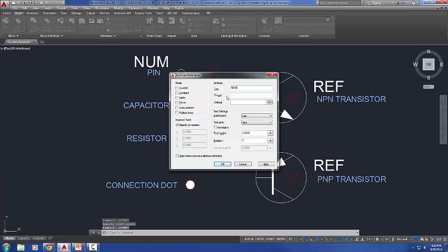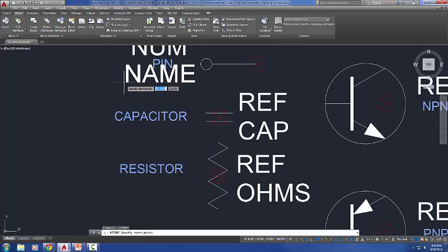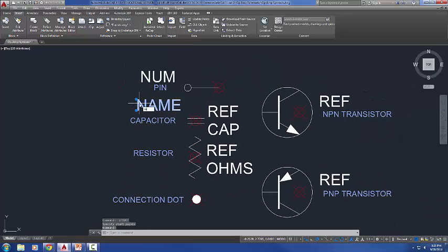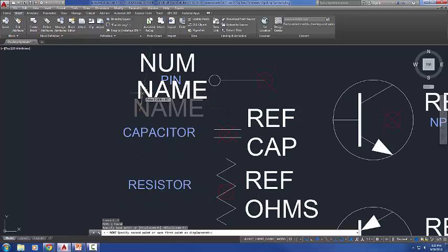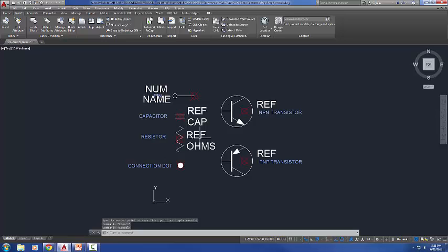Now what I need to do, and what we're ultimately going for, is a named view. The only thing that's going to be different about this is I'm going to check where this has multiple lines. So instead of me typing one line of text, this will give me the option to do multiple lines like a text box. I'll say OK to that. Say new. There's a few things that you have to do here. Put my view name, I'll call this East elevation.